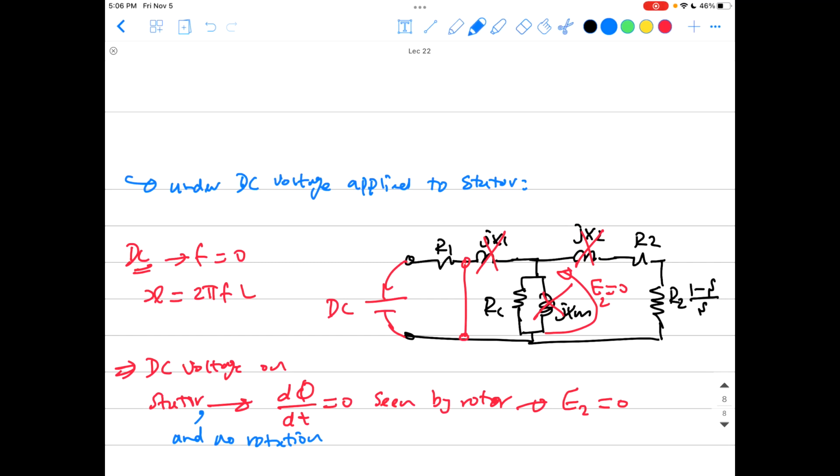The change in the magnetic field comes from two sources, guys. Number one, if it comes from an AC voltage, it's changing by nature, like in an induction machine. Or it comes from DC, which is not changing by nature, but it's rotating, like in a synchronous machine. Remember, the magnetic field from the rotor of a synchronous machine comes from DC excitation, so it's not changing by nature, but you apply rotation to the rotor, so the stator winding will see it as varying with time.